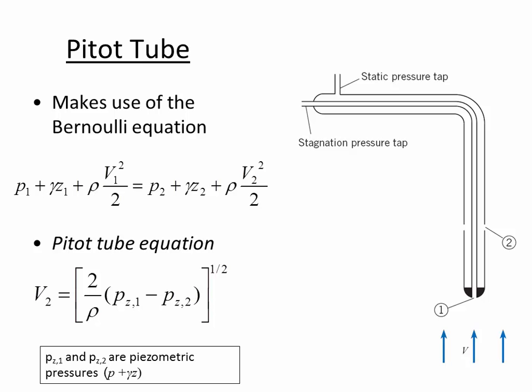So that's why it's pointed sideways instead of immediately into the flow. If it's pointing sideways, then the streamlines just go past it. There's no stagnation like there is here, when it's open to the streamlines and it's trapping some of the streamlines in the opening there. Since it's sideways, the streamlines just continue past, and so the pressure that it measures there is only whatever the atmospheric pressure happens to be at whatever elevation this is located.